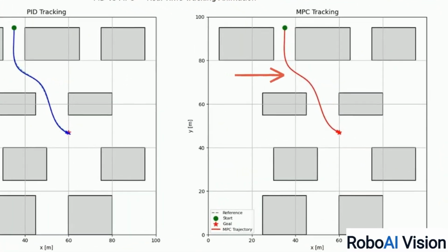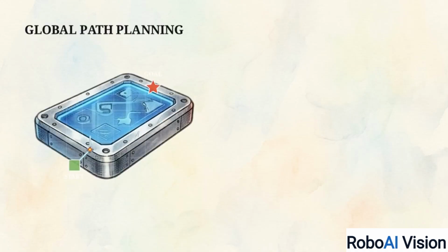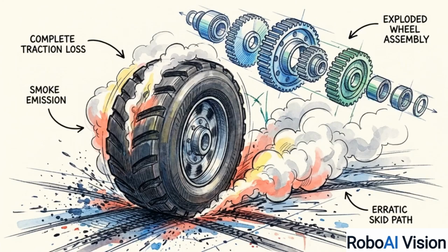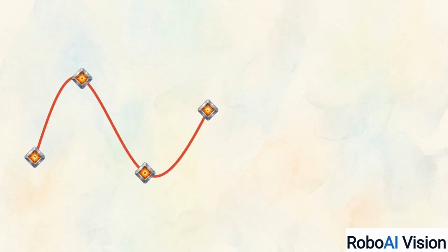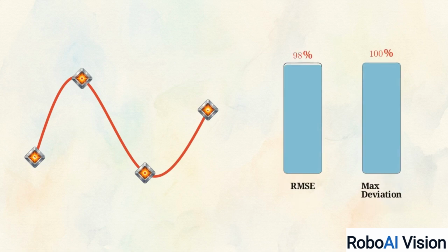On the right, the smooth red trajectory cleanly navigates the obstacles without oscillation, representing a fully integrated path smoothing and predictive control pipeline. A path planning algorithm that finds a mathematically valid route to a goal does not mean a robot's physical actuators can actually drive it. By combining an A-star search with line-of-sight pruning, continuous curvature smoothing, and tuned motion control, we can reduce trajectory tracking errors by 48% and cut peak maximum deviation by 62%.